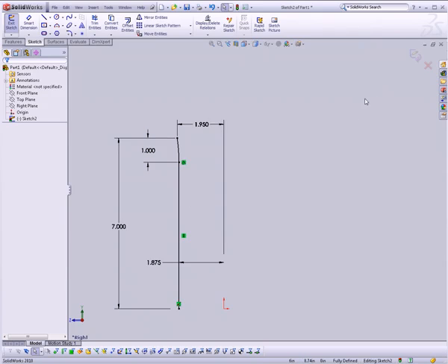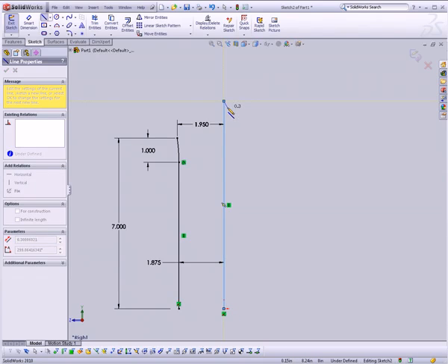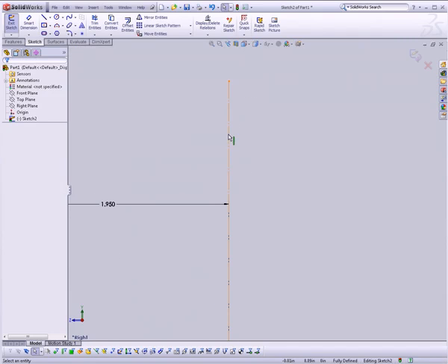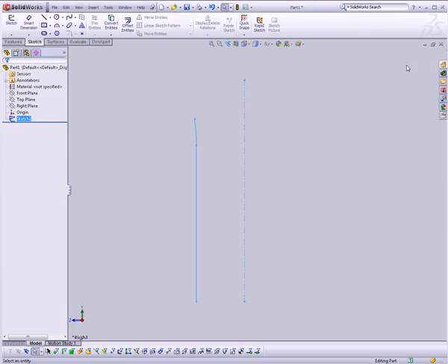One more thing we need to add is in the middle, right here. I'm just going to hit Escape. Now I'll select this item, and I want to set it to be for construction. I can check the box over here in the line properties, or I can click the line once in the viewport and come up to construction geometry in the context menu. That's just going to give this a phantom dashed line, which we'll be using as our center line when we revolve. So we'll go ahead and jump out of that, and we can go back to our default view. We can do that up here, or like I said, we can right-click in the viewport and just drag up diagonally.